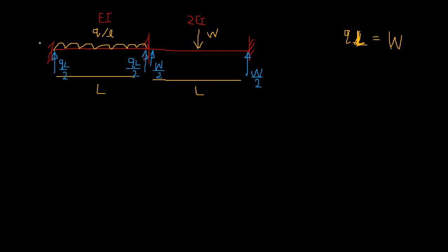And you know the fixed-end moment, right? So I'll take clockwise positive, always clockwise positive, so that means clockwise bending moment. Here actually you have an anti-clockwise, so the sign is negative then, right? If you draw it in the anti-clockwise direction, it's positive sign, because you already mentioned the correct sign. Here I'm always taking clockwise. If something is negative, that means that is anti-clockwise, right?